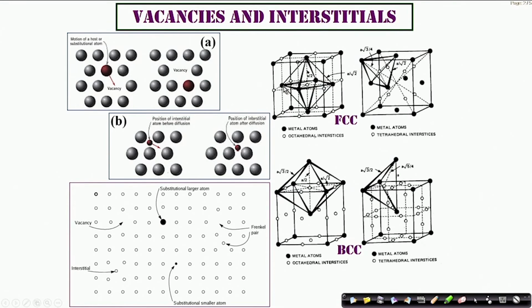But when you say that you expect atoms to occupy corners and face centering positions, then the centers of the edges and the center of the cube, or center of the unit cell, obviously are lying vacant. And the diameter of such a vacant hole is the largest. So this is how you can define a possible interstitial vacant site and its size in an FCC crystal.